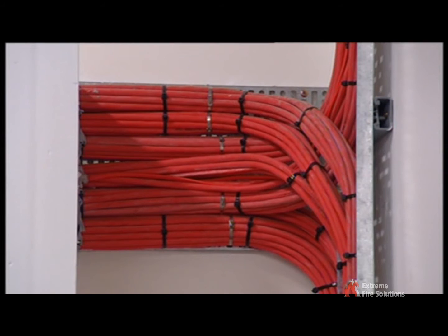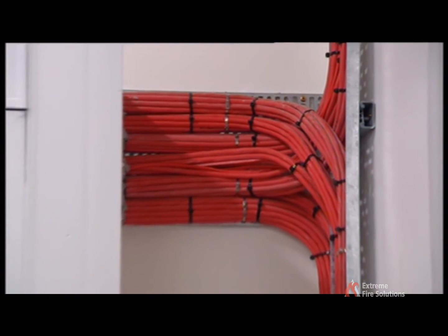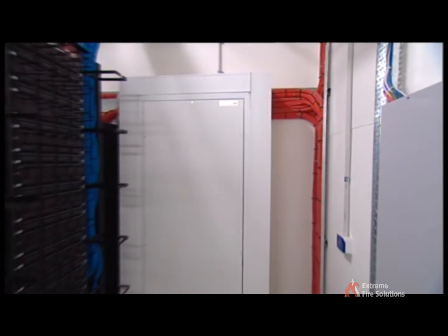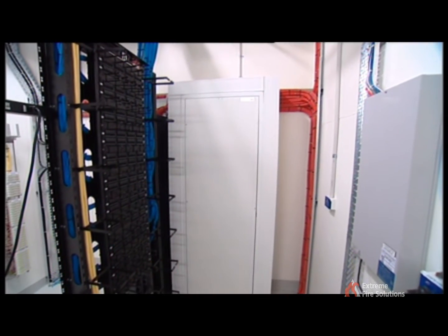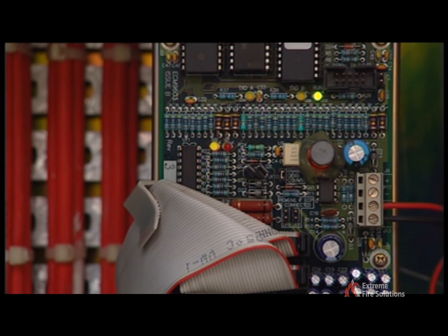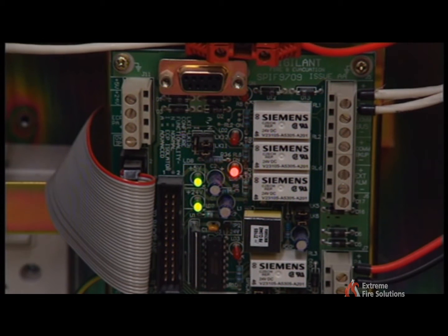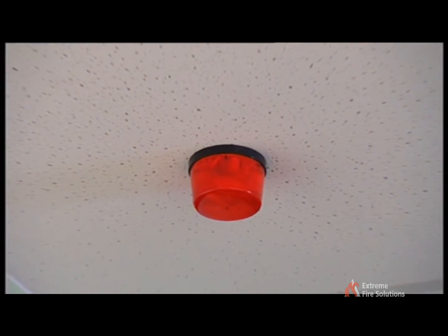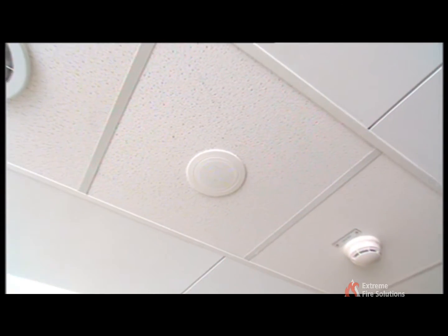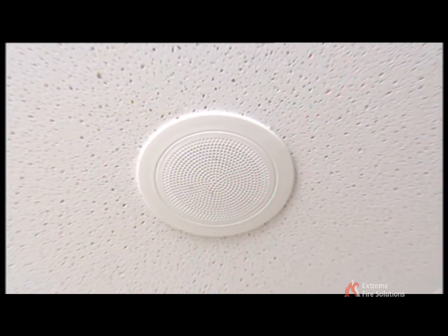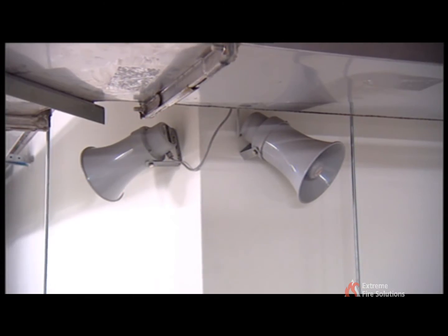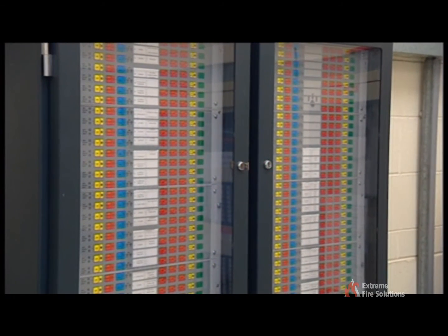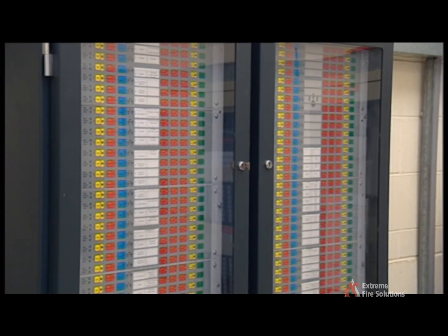The EWIS comprises a networked amplifier rack, also known as a data gathering panel or DGP, installed within the communications room on level 5. Housed within this panel are all the amplifiers required for each floor to transmit alert and evacuation tones in the event of an alarm. Connected to the amplifiers are speaker circuits for each floor. This DGP is networked to the main emergency control panel within the fire control room.